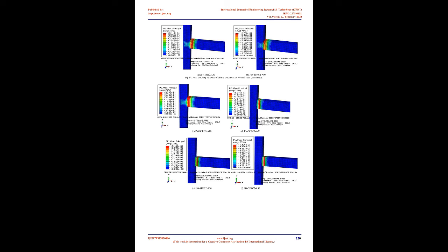The hysteretic loops obtained from the nonlinear finite element simulation of specimens with different column axial load ratios are shown in Fig 11, A to H. The increase of column axial load level from 0% to 20% of column capacity resulted in an increase of some extent, approximately 1.3%, of the peak load carrying capacity of the specimens. However, when the axial load level is more than 20% of the column capacity, the lateral strength deteriorates slightly due to the development of greater compressive shear stress in the joint area.